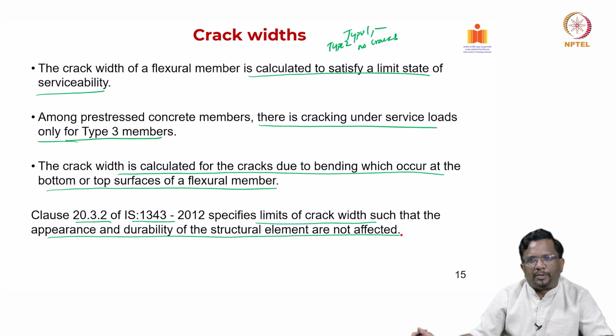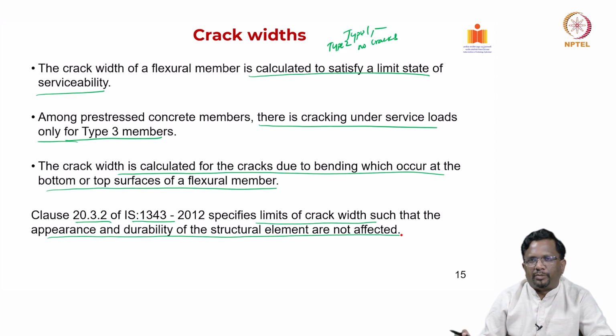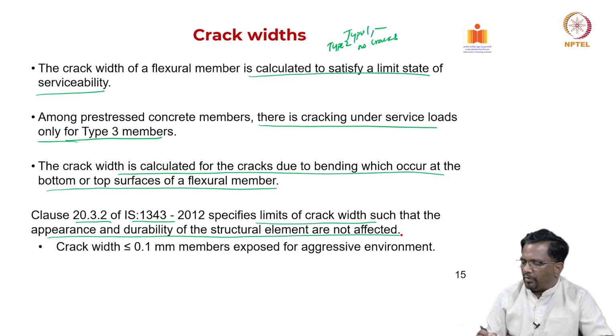Okay. So, typically in a pre-stressed member, it is always better to go for a design where, under service load, it should not crack. Then you can use the entire amount of inertia in your deflection calculations, and also the durability performance will be much better. Now, what are the limits?